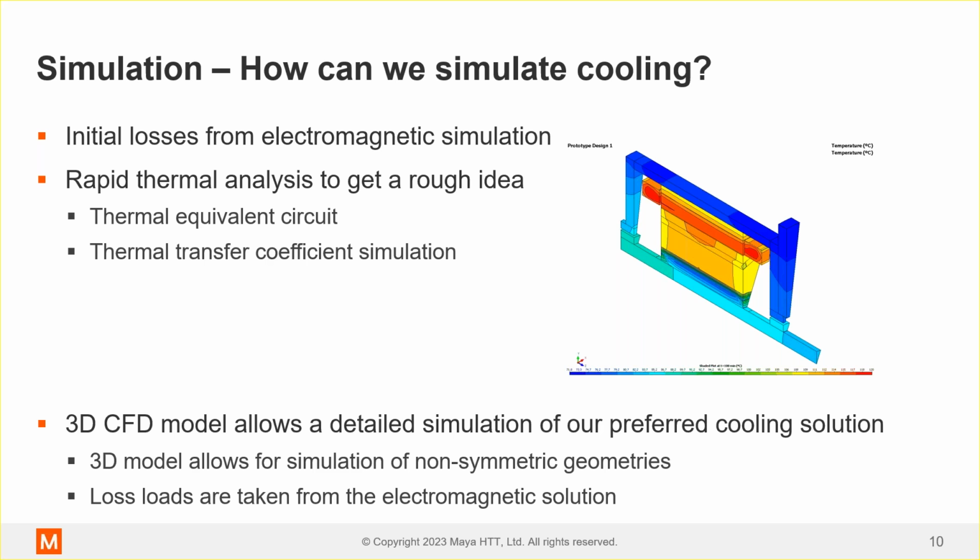We can do a basic thermal analysis with thermal transfer coefficients. So this is a slightly more detailed design or slightly more detailed simulation where we're going to look at the losses, how things spread in the individual components. But we're not going to do a CFD, which can be fairly computationally expensive, fairly time expensive, and we'll just substitute in that with thermal transfer coefficient. So effectively, how easily the heat energy can transfer between components.